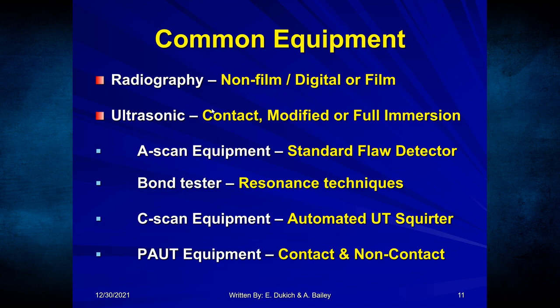For radiography, for the equipment selection, radiography uses an X-ray machine, or we can use something called gamma, which is a radiography source that never turns off. It's a source of radiation. Now, if I'm using a camera or a machine, we can turn it off. And the radiation source penetrates the specimen, and we can capture the information by using non-film techniques, which we call digital radiography, or film techniques, which are using conventional film, just like at the hospital.